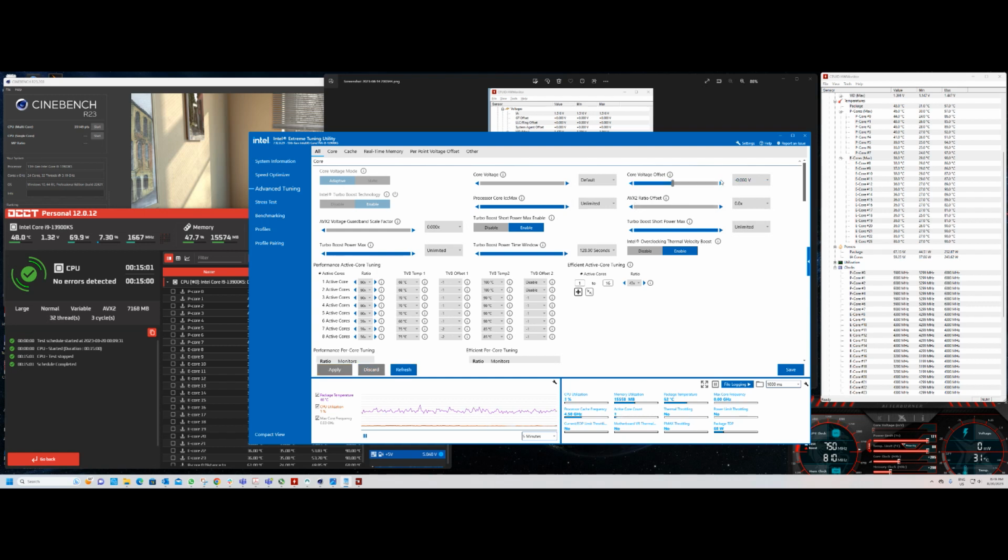You have the option to decrease it or increase it. In my case, I was able to get to my desired amount, which is negative 0.080 volts here. The core voltage offset allows you to apply that to the main core voltage and allows you to undervolt. It is highly recommended that you start by increments of 10, then start going by 5, so you can find a specific stability, find the number that works for you, start decreasing, increasing, and then make sure that you are doing benchmarks.